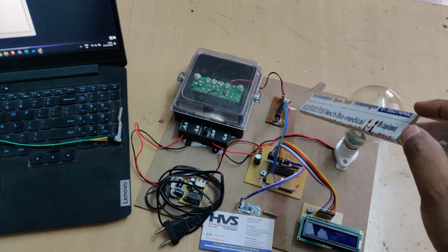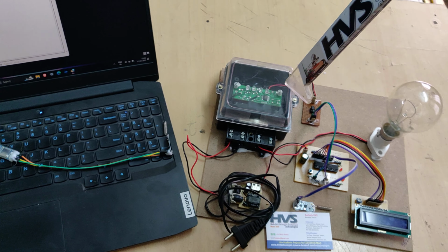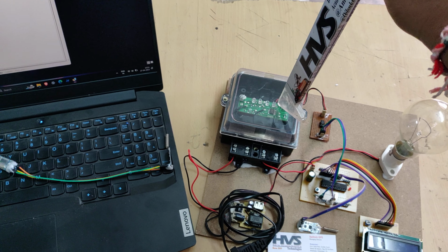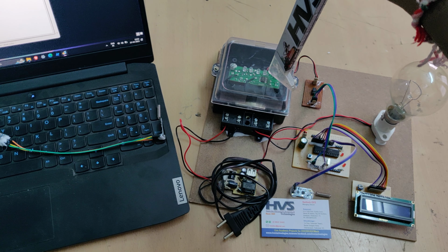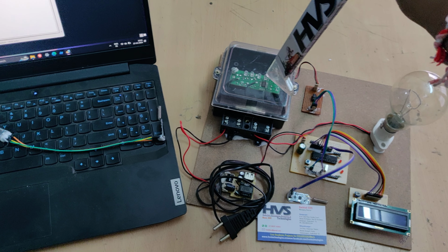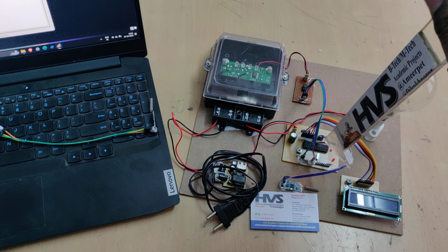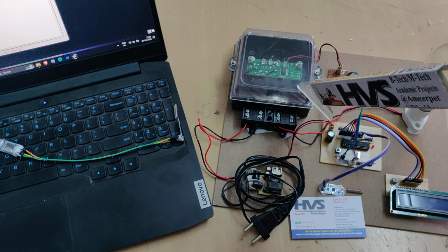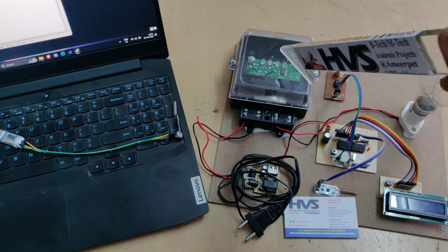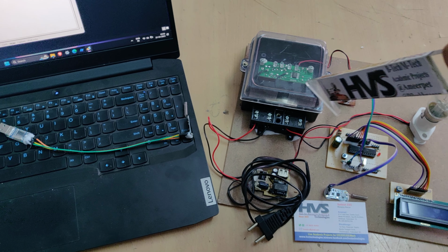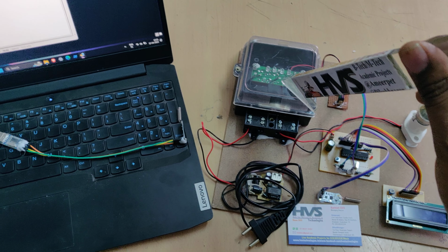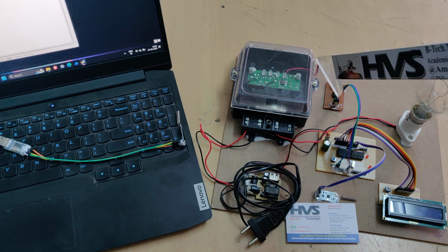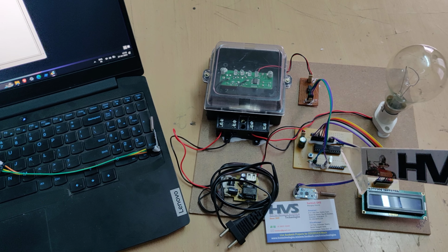So here the purpose of the optocoupler is, we are going to calculate the number of blinks from this LED. The LED gets only DC, so if we give that DC output from the LED directly to the microcontroller, and if any damage occurred inside this energy meter, then the AC voltage would pass all over through this port, and the same 230 volts AC will be given as input to the microcontroller through this LED connections. Then there is a chance of microcontroller damage.